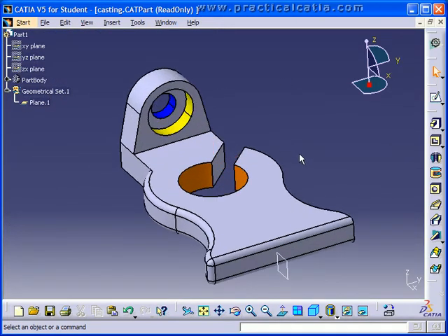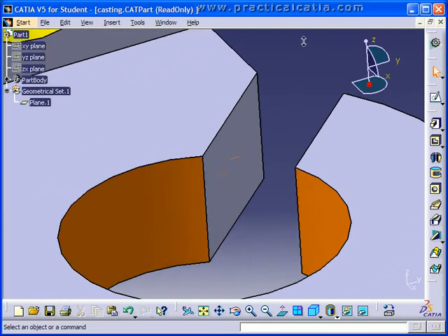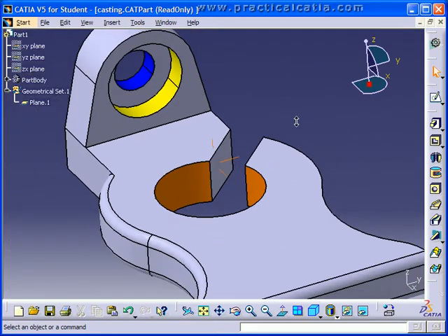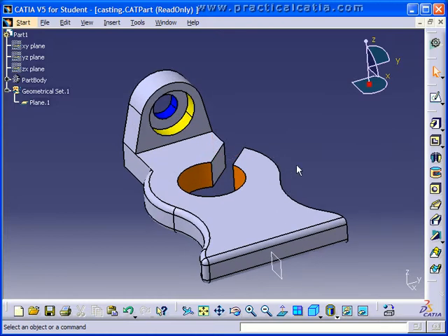Let's do that one more time. You place your cursor anywhere on the screen. I like to place it in the middle because if I move it up, then I can zoom in, and if I move it down, I can zoom out. You depress your middle mouse button, and while you continue to hold it down, you click and release your left or right mouse button. If you push your cursor up, you zoom in. If you push your cursor down, you zoom out. So let's everybody minimize the presentation at this point and experiment with the zoom in and zoom out, and also use the mouse to do zooming. When you're done, come on back to the presentation.